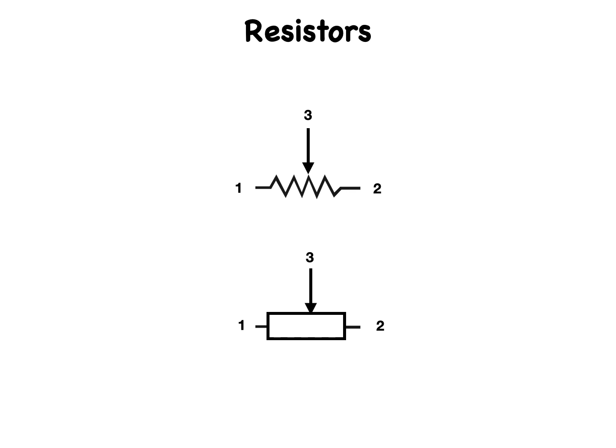Rheostats are in effect the same as potentiometers, but mechanically they differ. A rheostat contains a wire-wound resistance element, while a potentiometer is normally of the carbon composition type. Therefore, a rheostat's value varies in small increments or steps, while a potentiometer's value can be adjusted over a continuous range. In schematic drawings, an arrow often indicates variable properties of a component, but not always.